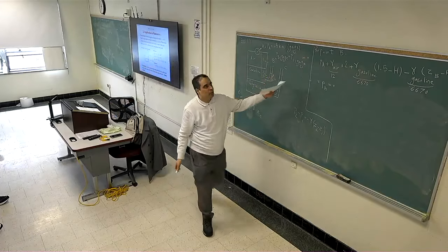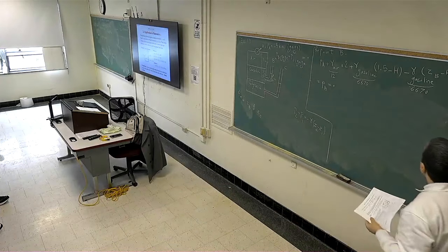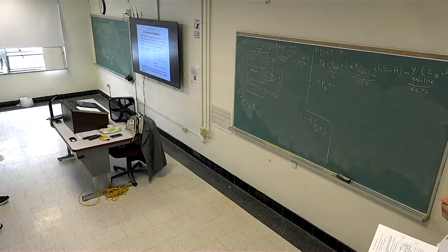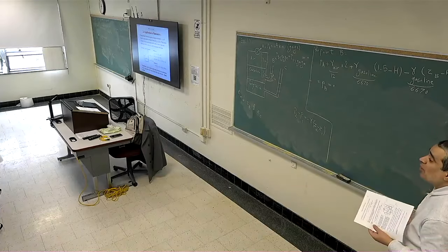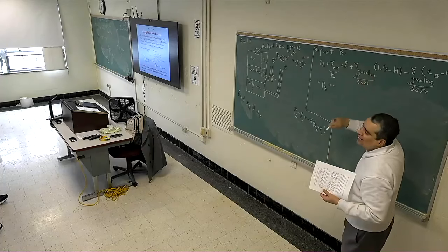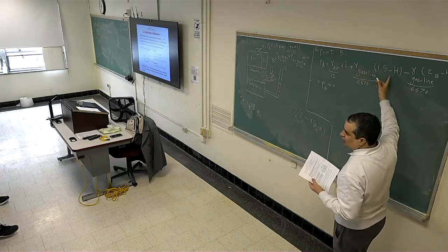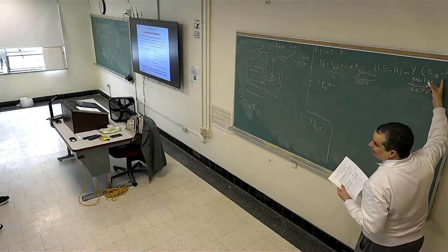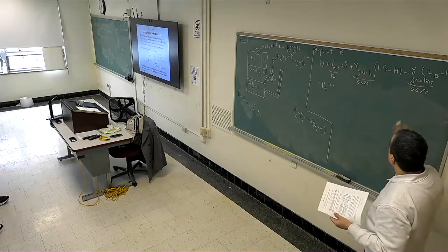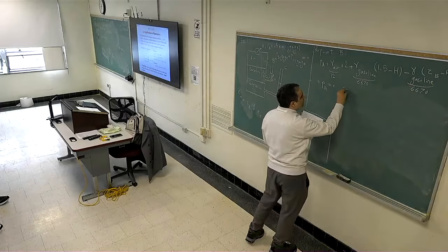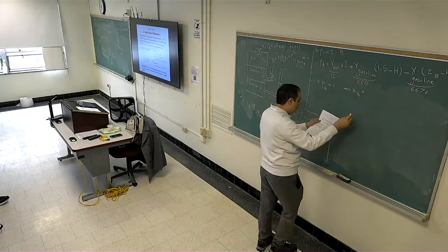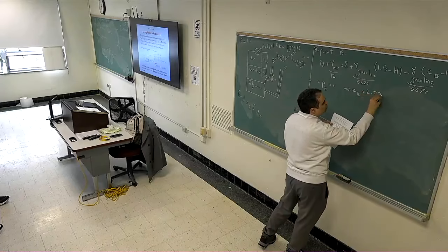Okay, how many unknowns do I have in this equation? 2. What are the unknowns? Yeah, H. But we are lucky that H cancels out. Positive gamma minus H, minus gamma minus H. So the H cancels out, and I can solve this and find ZB as 2.73 meter.